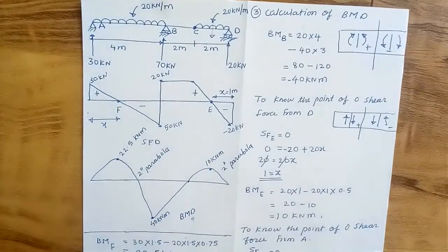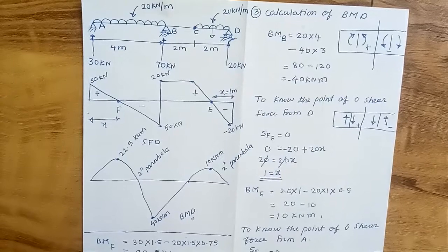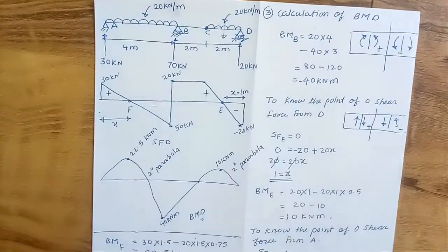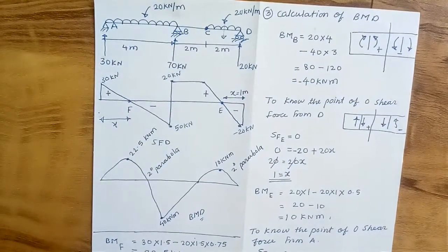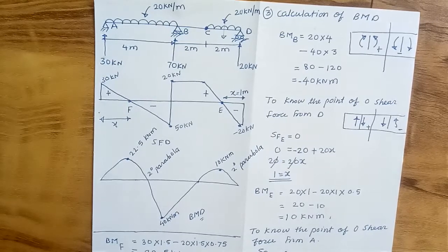For this calculation. Okay, so this is how we have to draw shear force diagram and bending moment diagram. The only difference in this problem was that at point C there was a hinge, and as we know, a hinge allows the rotation, so the bending moment at hinge will be 0. So that we got an additional equation, so that's why we could analyze this beam.